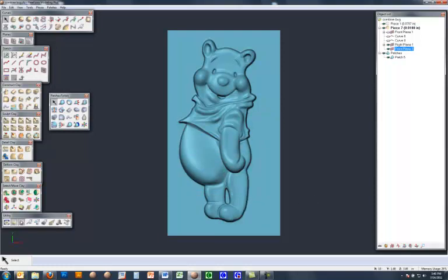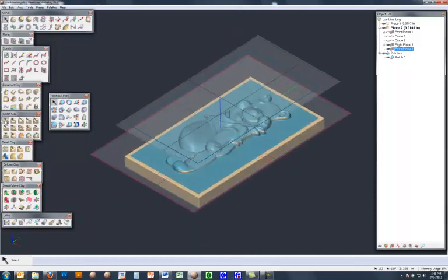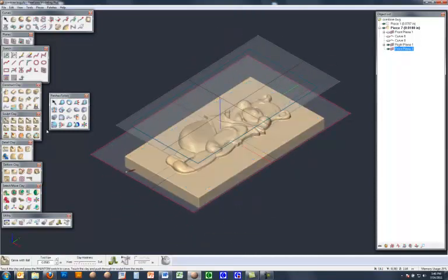Now I bring back the clay and the plane, get out of the command and just hit undo. And then this time I'm going to redo the command, but look at the solid option instead of the surface option. So again, pick the sketch loop, pick the limiting plane,